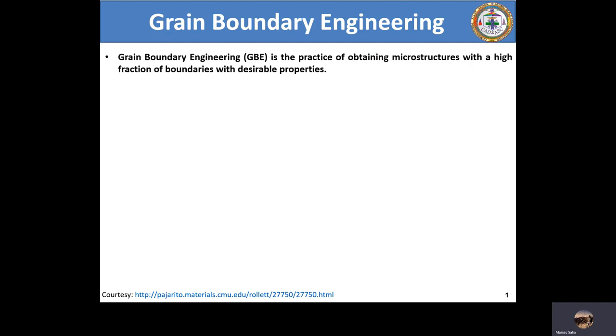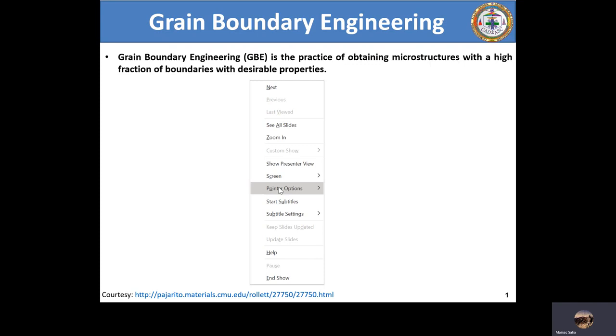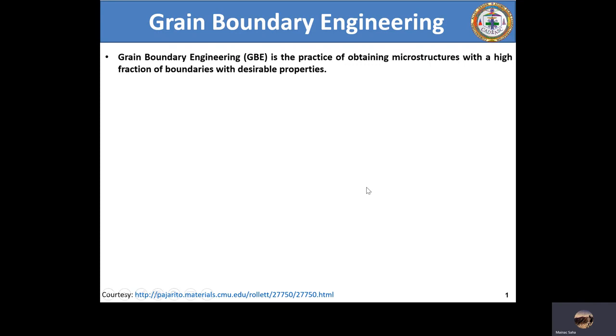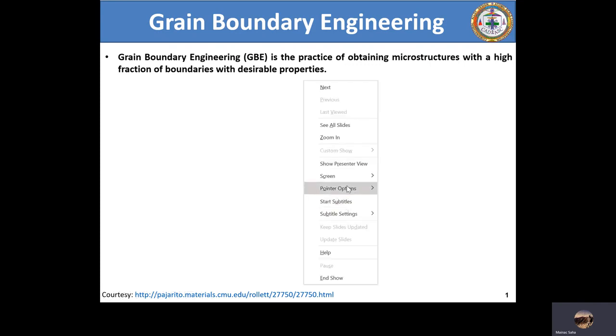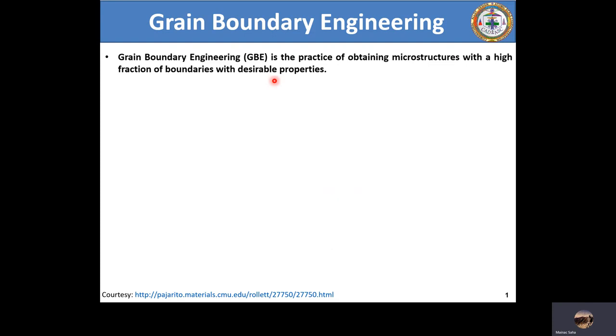And of course, the reason behind that we have also covered in one of the earlier sessions. Then we have also discussed how a typical grain boundary energy versus misorientation plot looks like, where in a cubic material there is a 4-fold and 3-fold axis of rotation, and as a result we have some symmetry in the grain boundary energy versus misorientation plot.